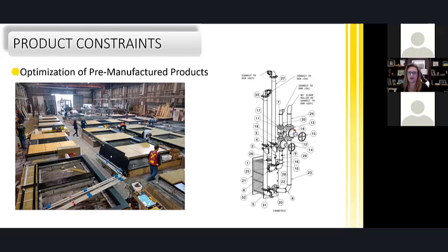We always try to optimize our panel sizes, because obviously we have a size of a crane, and the larger the panel, the faster the installation goes. We also consider how many times we pick from the crane. We generally can do 36 picks in a day. And if we can manage to do our entire floor plate and our walls, because we're using CLT walls and some columns, all in one day, that's a 1-day cycle. And then we do our envelope panels in 2 days, that's now a 3-day cycle. So every day that we're doing multiple picks, it can actually delay the project by multiple days.